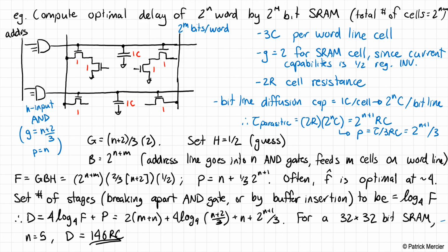So again, this is an interesting example where we take a little bit of what we learned in logical effort, and what we learned today about SRAMs and decoders, and use it to make a design that had pretty good or near optimal sizing, at least according to the assumptions that we've made here.